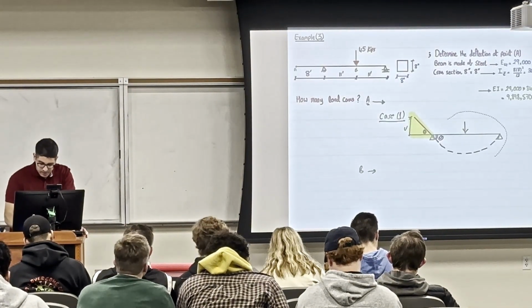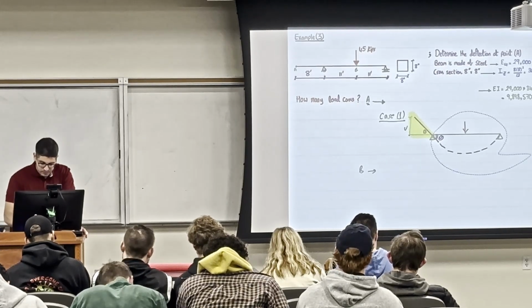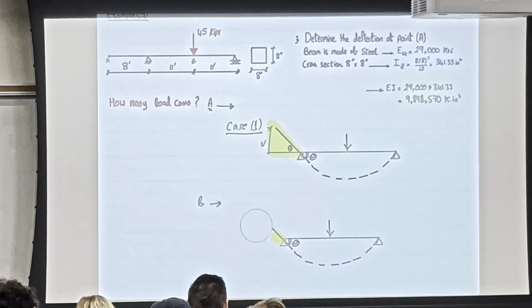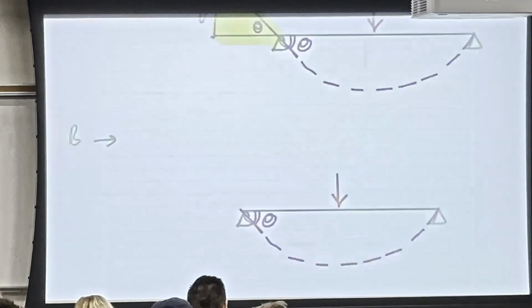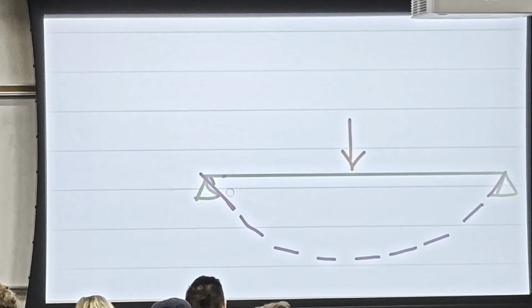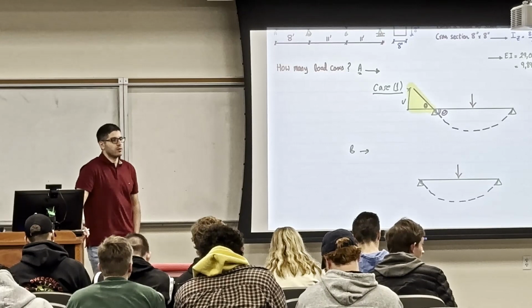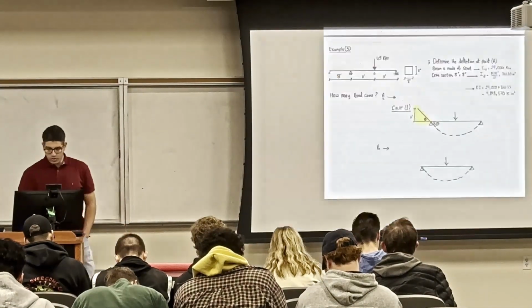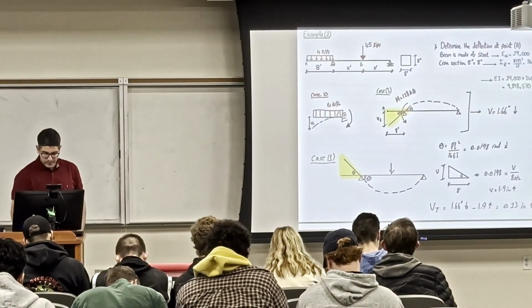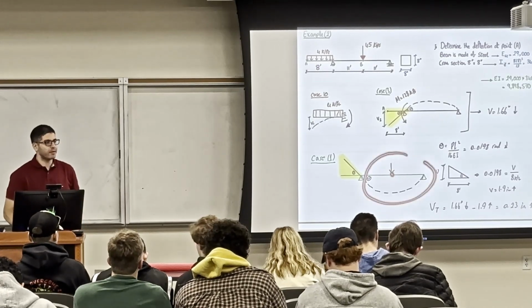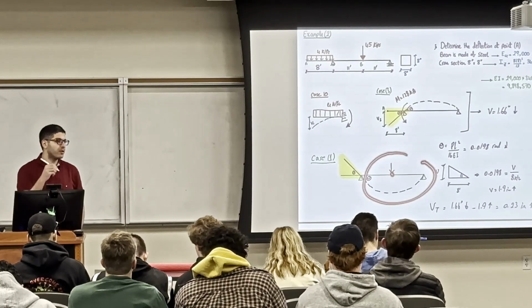So you're gonna take that one for point B, and I don't need to do the extension part, and I don't need the theta. It is just at point B, which is at the midspan, you're gonna use the Vmax equation. What's the difference from the one that we just did above when it was 2? Here, you wanted to find B, right? So for B, we're gonna use that one because we already have the point load in the middle, so there is an effect that the point load will do.